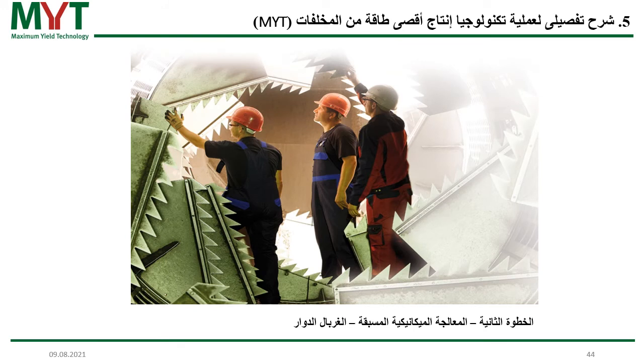Here you can see the drum sieve with the back openers, with these claws, how big this is. With this drum sieve, we create 3 different fractions. Like I told you, the first one is the small fraction, where most of the organic is in. This fraction is not sorted by hand, only magnets take away the metals which are still in. And the big part with the fine fraction with the organic goes directly to step number 3.